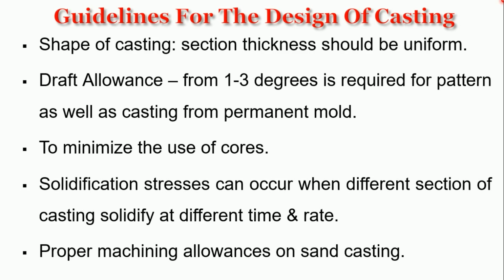Second, sharp corners and angles should be avoided because they are sources of stress concentrations and may cause hot tearing and cracks in castings. A fillet should be designed on inside corners and sharp edges should be blunted. These are some of the design considerations in the casting processes.